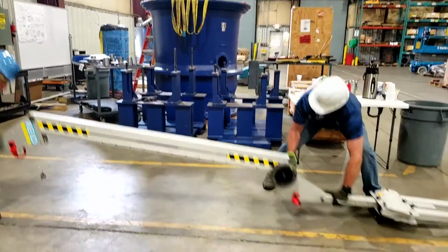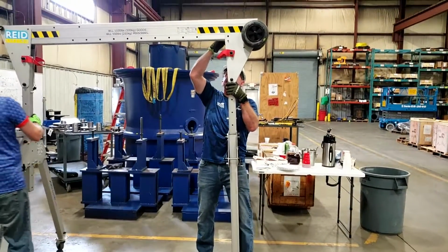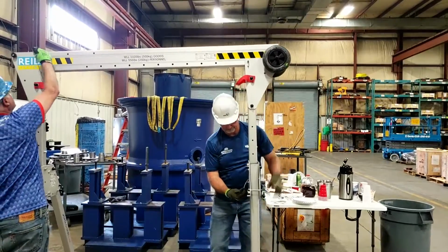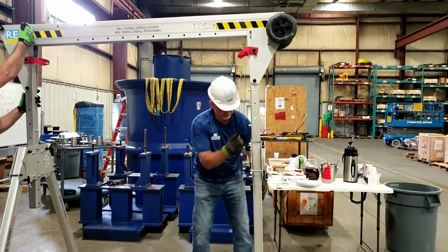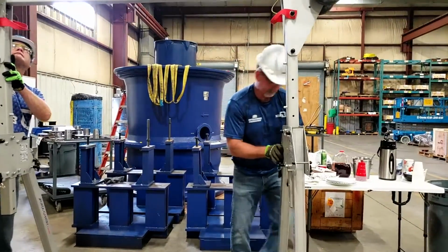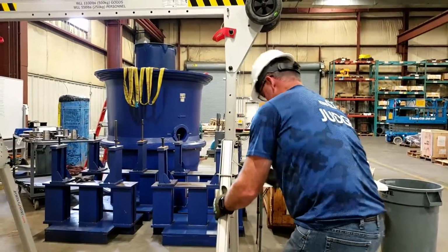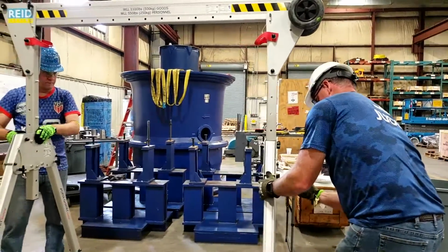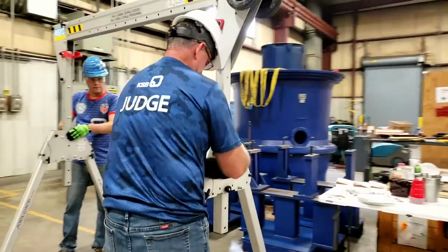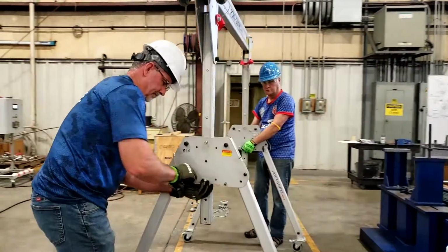The legs on each end will also need to be unpinned, angled out, and then pinned in the proper locations. The gantry height will also need to be fully extended such that the riser bottoms are flush with the cross support on each leg. Ensure both bolts are installed on each end of the gantry. It does not matter which 2 of the 3 holes are used for the bolts when assembling the gantry.